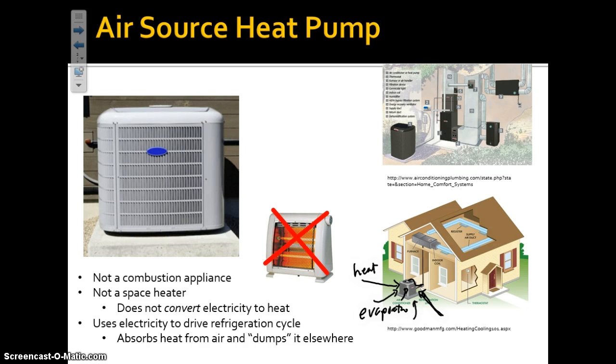And then it goes through here, your refrigerant line, and in this case it's releasing the heat into the air inside the duct, which then circulates through the duct and the heat comes out here. Same principle: in heating mode, it's pulling heat from the outside air, and that refrigerant goes through your refrigerant line and into, in this case, a hybrid system. So this also has a natural gas line.